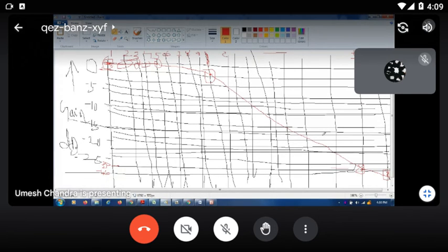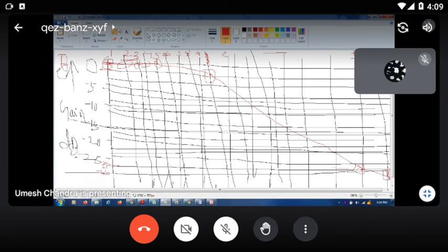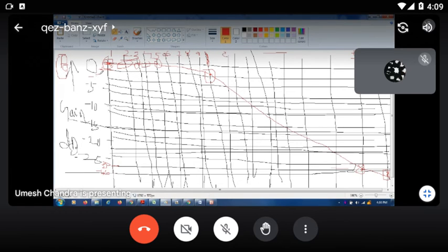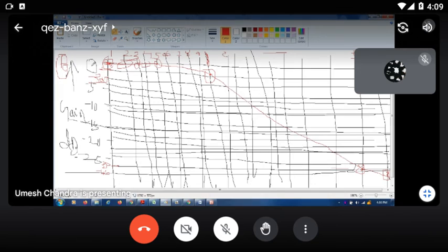Then after that, you calculate their cutoff frequency, FC. And how do you calculate the cutoff frequency? The cutoff frequency is at minus 3 dB. Here is minus 5. Between 0 and minus 5, you take the minus 3 dB level. All are in dB; gain is in dB, minus 3 dB.